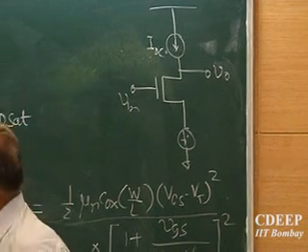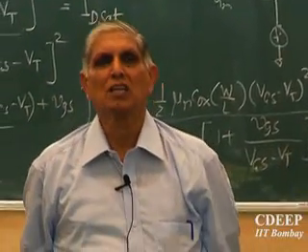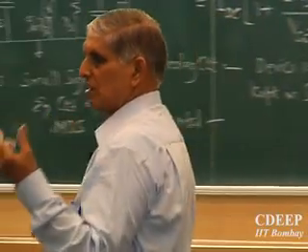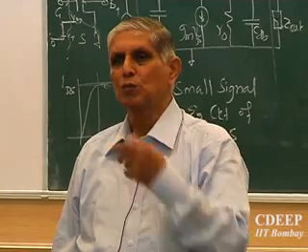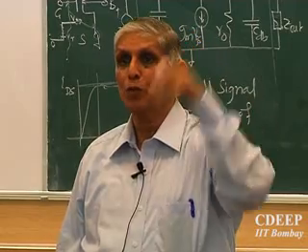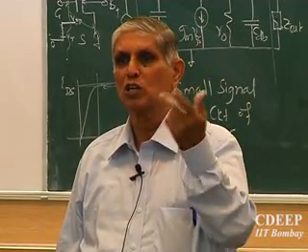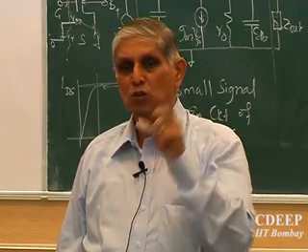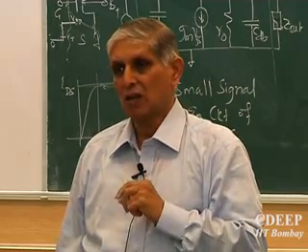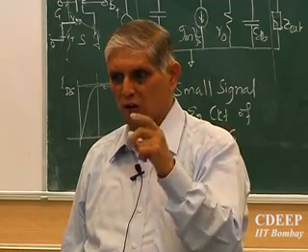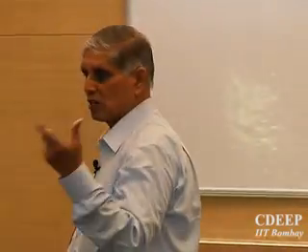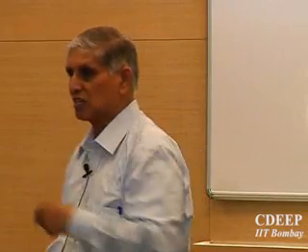I have not done technologies very much, so you will not immediately appreciate. A resistor is made out of some diffusion area, either P area or N area, and the resistance is proportional to what? Rho L by A. Is that clear? So rho, which is decided by the doping, is 1 upon q mu N or q mu P. So the doping decides the resistivity and size decides the total resistance. So if you want 1K to 100K or 1 mega ohm, the size of this resistor will be so large, for the given P and N we can dope in a technology.